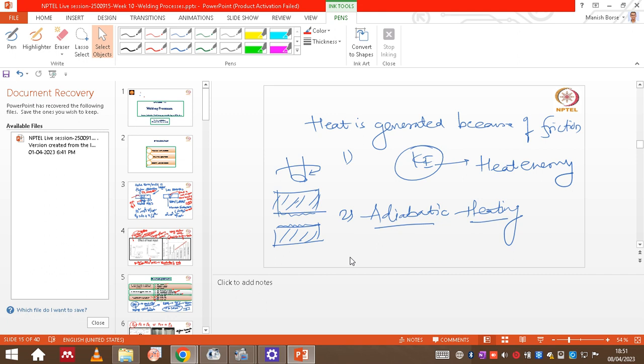Then at that time the softened metal won't be sufficient to fill that cavity, so that kind of defect will form. But microporosity it won't form, because metal is actually flowing significantly from one side to another side. So it will eliminate porosity.